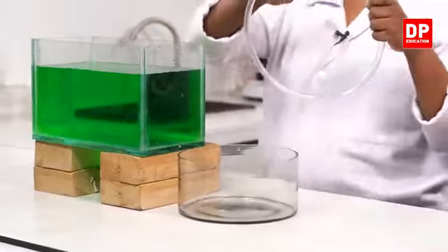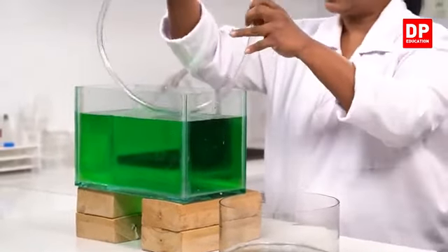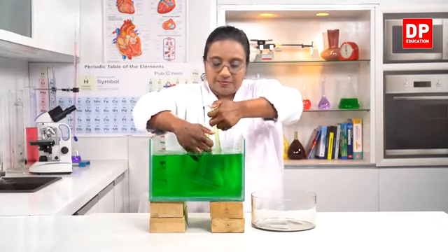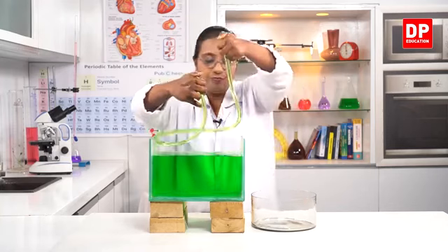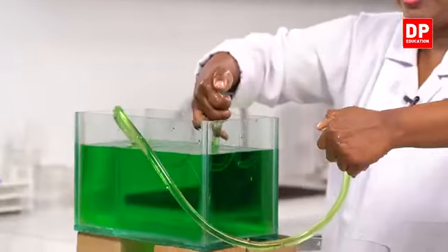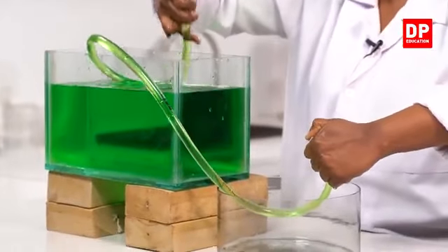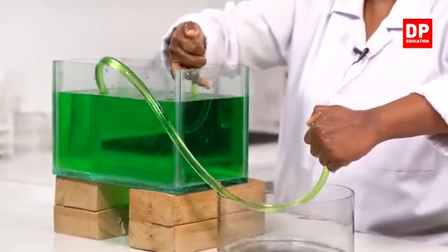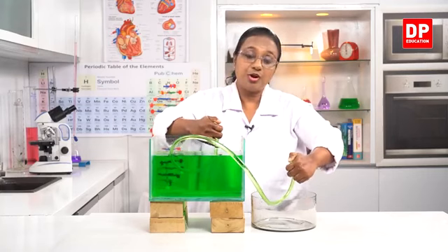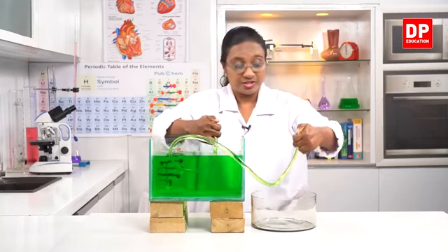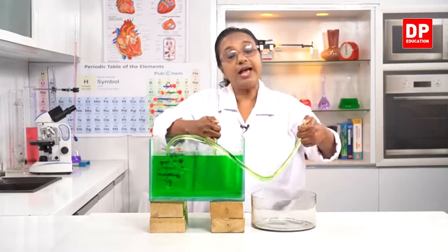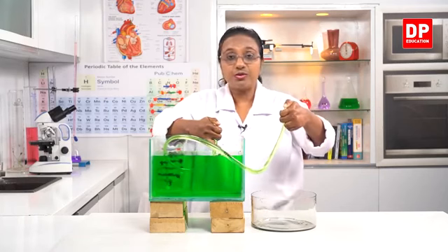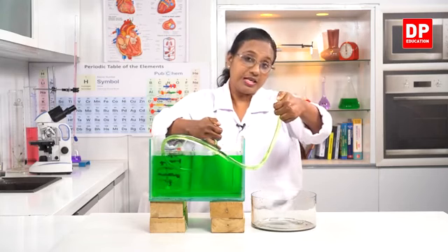Here, what I will have to do first is fill this rubber tube. Now there is water filled in the tube. I will have to bring one end to the second tank, and the other end has to go right to the bottom of this tank. Then, as I explained before, there will be a difference in pressure. At this end, it's only the atmospheric pressure. When I release my thumb, it will be exposed to the atmosphere, so there is only atmospheric pressure acting on this end.